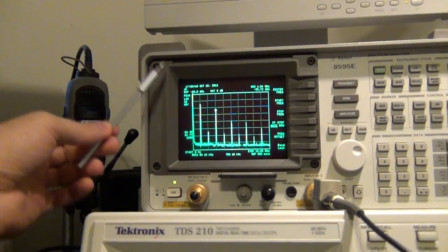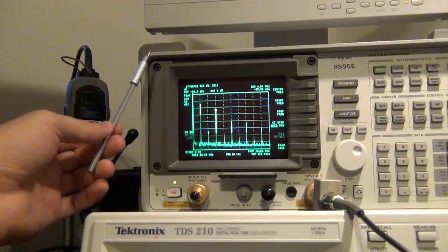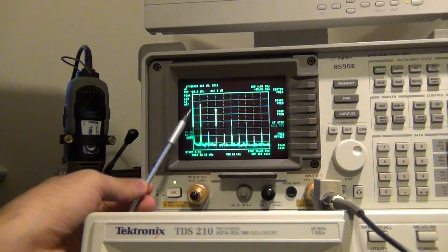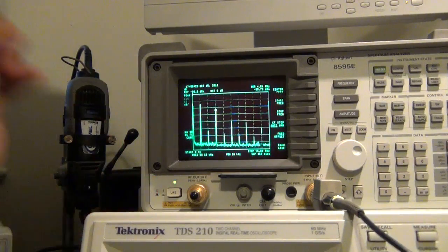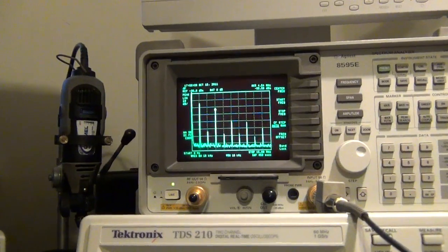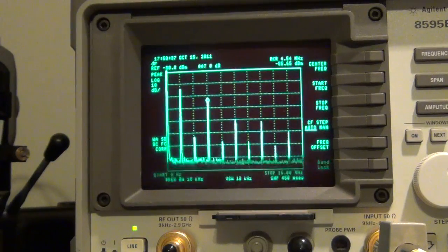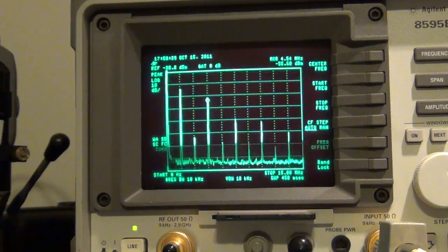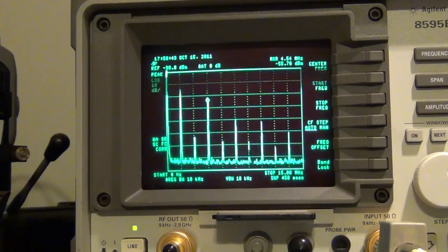These type of circuits are built all the time. For example, a frequency doubler, frequency tripler, and so on. So if I build a proper filter here and a proper filter for the output, I can put in 1.5 megahertz and get 3 megahertz. So that would be, for example, one application of having a nonlinear circuit. And of course, the main application for having nonlinear circuit is to build mixers which do frequency translation. So I'm going to leave mixers for a different tutorial.